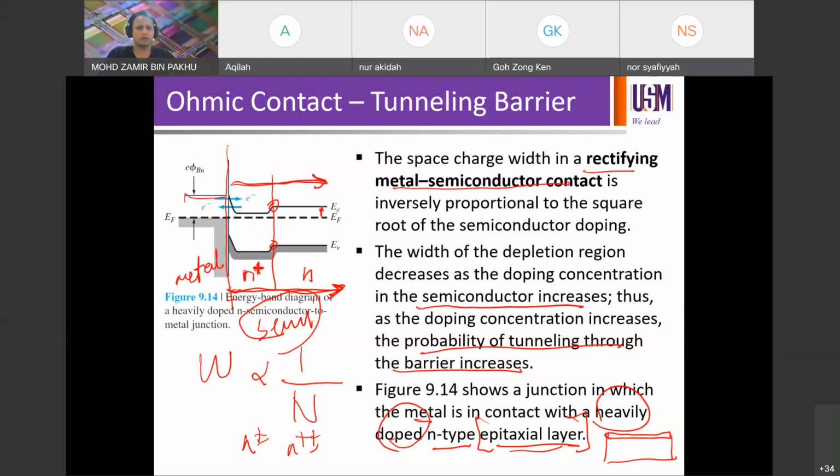So for the N-type, yes, you can have that distance just to set the reference, if you like. But if you increase the doping for the N to be N plus, close to the surface there, that means your EF in the band diagram should be closer to your EC. You can tell by the distance there and by the distance here in comparison.